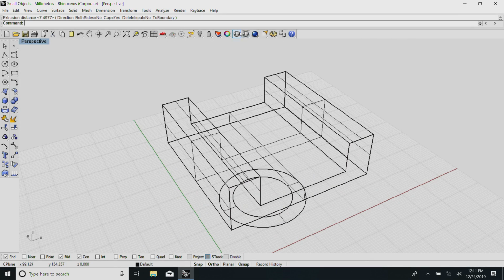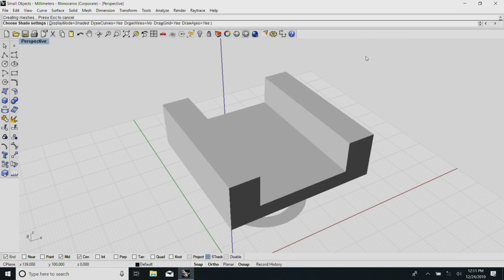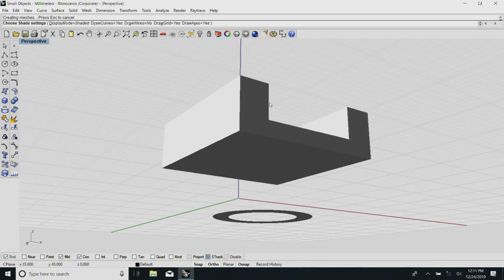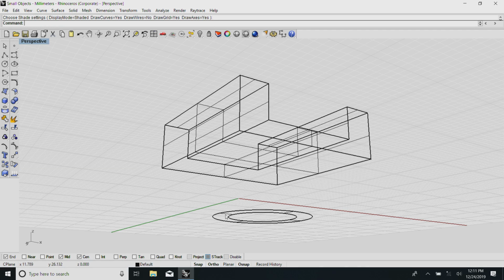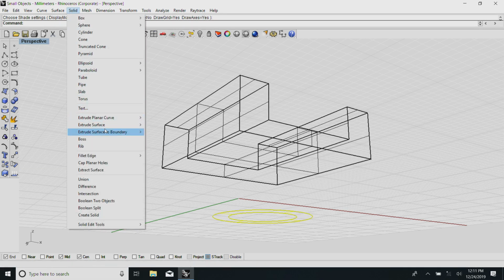And why one is preferred over the other is that one was based on a 40 mm square of length 36 mm. In this case, let us say I already have, usually, an extrusion of the nearest size. Imagine I have a C section which approximately has the same dimensions here. I can use this C section, cut it to length, and at the other side I have a small pipe, and pipes of various diameters are already always available.